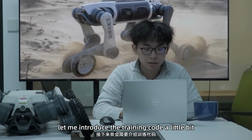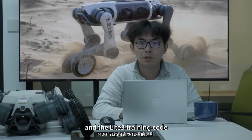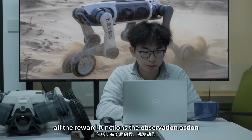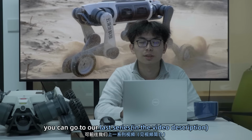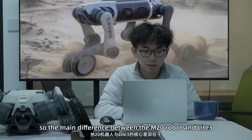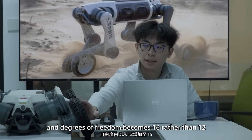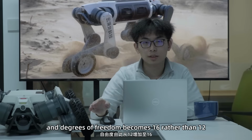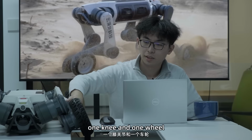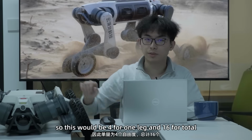Let me introduce the training code a little bit. I'm only going to introduce the differences between the M20 training code and the Lite3 training code. If you are curious about the details of all the reward functions, observations and actions, you can go to our last series to check the detailed training code explanation. The main difference between the M20 robot and Lite3 is that we have wheels here, and the degrees of freedom becomes 16 rather than 12. So we have 2 degrees of freedom here, 1 knee and 1 wheel. So this will be 4 for 1 leg and 16 in total.